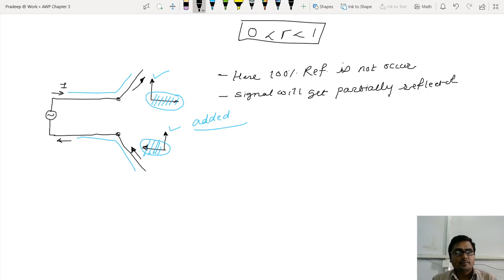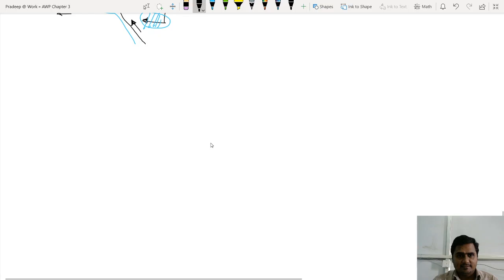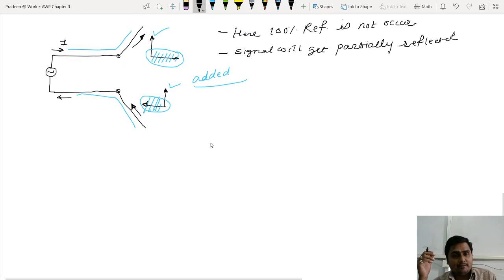Why is it happening? Because one current component is added, and then the strength increases. Now if the strength increases, obviously it gains the ability to go out from the wire, to detach from the wire, and that's why when you flare it, it will radiate and the reflection will be minimized. But I didn't say this is an antenna yet, because if I want efficient radiation,